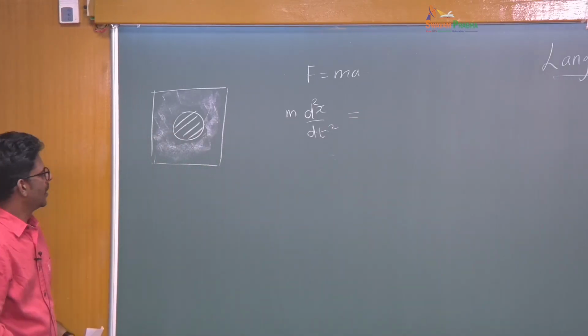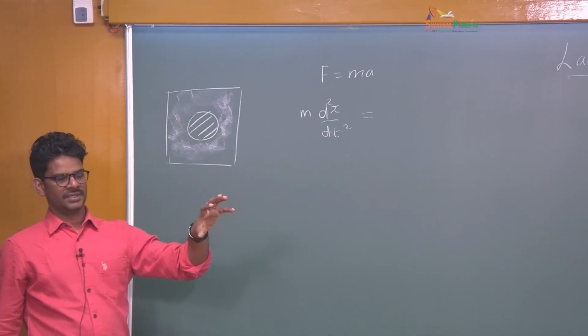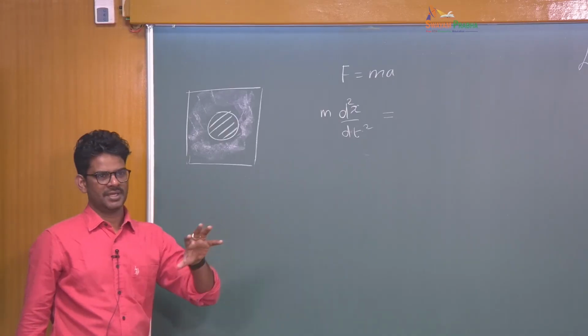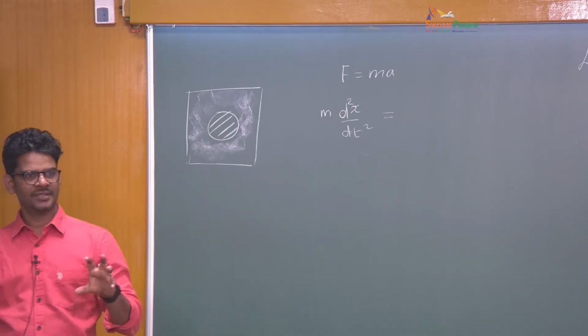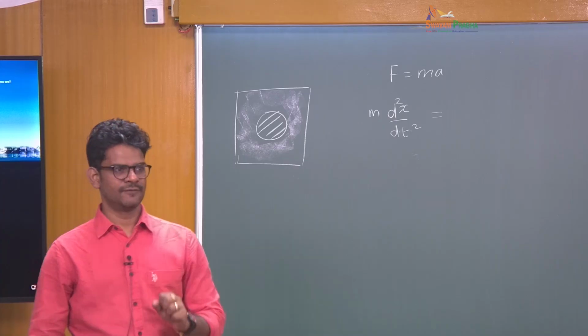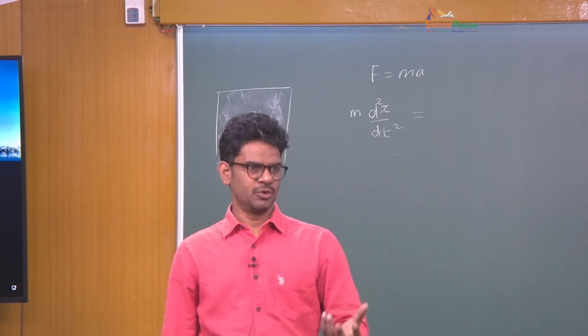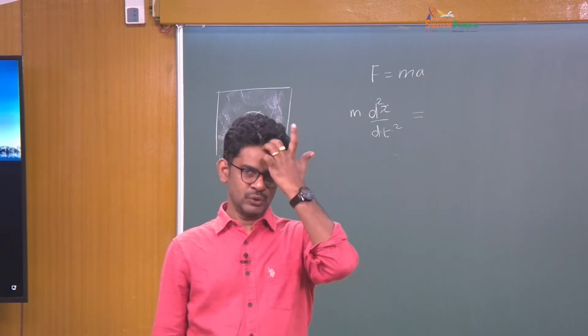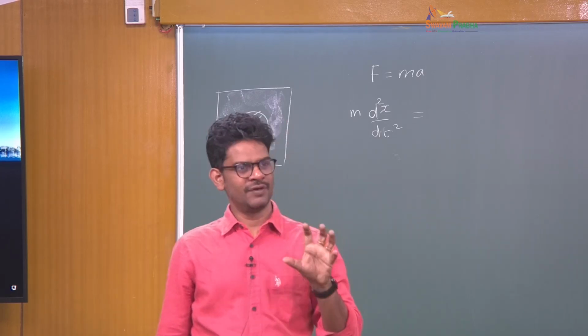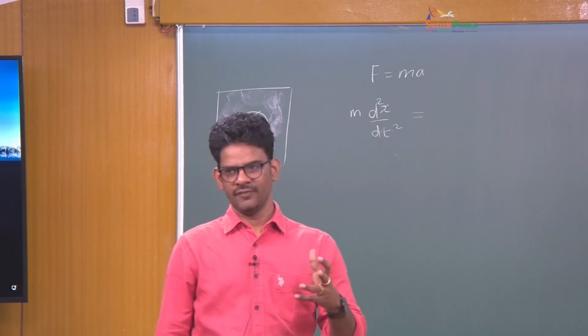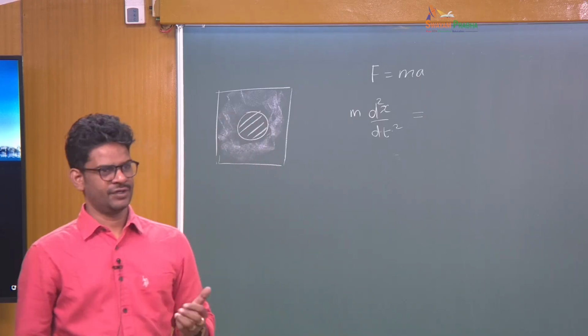Okay, so clearly when this particle moves, it moves in a viscous medium, and as chemical engineers we know that when an object moves through a viscous fluid, there will be a drag force acting on it to resist the motion. Okay, and we also know that the drag force is proportional to the velocity with which it is moving, with a proportionality constant called the friction coefficient.